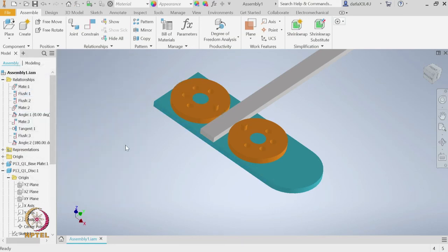So, in summary, what we have looked at in this lecture is first we have repeated the assembly of this crank and rocker mechanism, and then we have also looked into how to animate this assembly using the drive option. Later in the drive option we have seen, by changing it to a different problem, how to apply these parametric constraints, where we can write equations about how to apply these constraints.